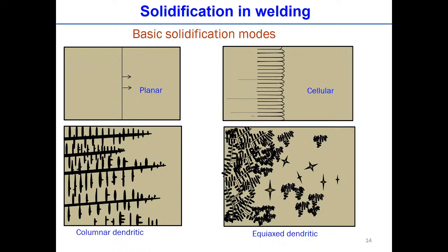If you see this figure, solidification starts at several positions at a time. It solidifies making this kind of dendritic, equiaxed structure. Then it grows, and there is a possibility that, in the dendritic structure, there is an entrapment of the liquid phase between the primary, secondary, and tertiary dendritic arms. So in that part, it solidifies at the last stage.